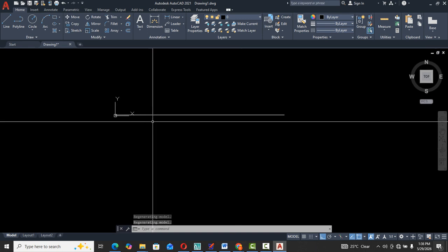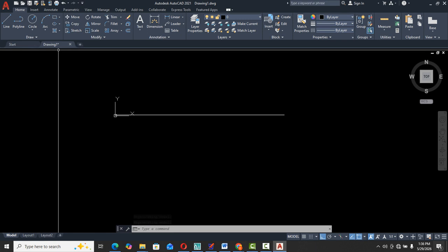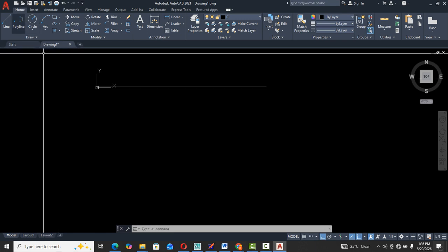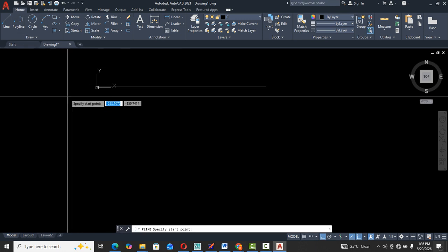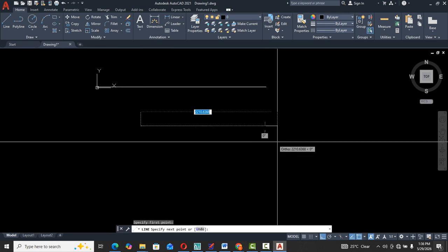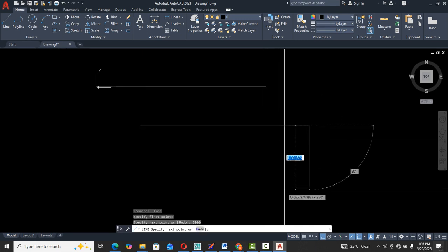Then your erase tool, if you put it there, you see it removes objects from a drawing. So when I erase, you see that the objects in red on the drawing were erased, so they're no longer there. So if you go to explode, it breaks a compound object into its component objects.